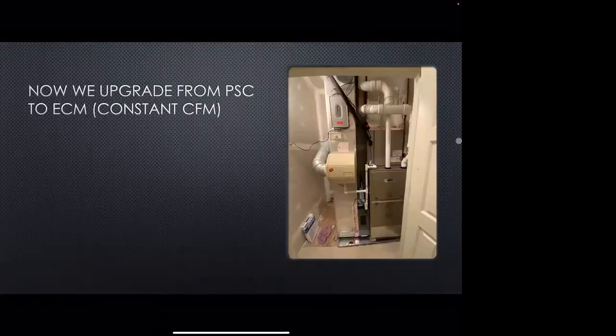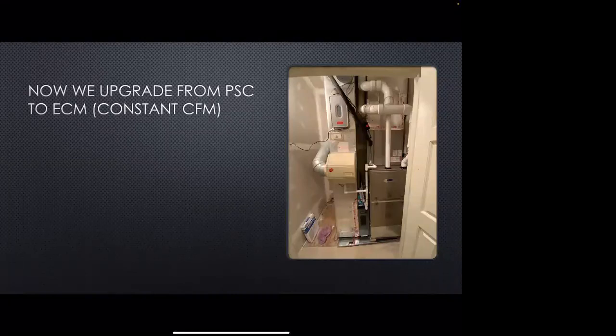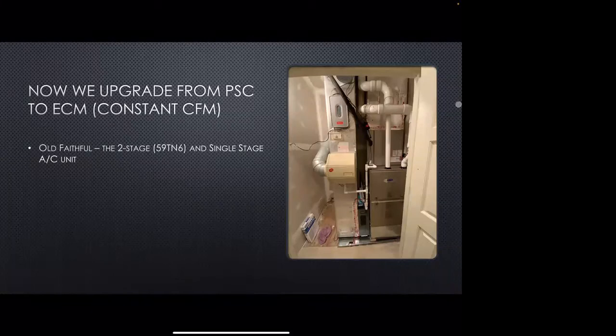So now what we do is, man, we got a furnace that has some impingement, some damage of the heat exchanger that's getting close. The homeowner's like, all right, let's just get rid of it. Let's get it replaced, right? I want to upgrade. I want a new furnace. And we go from a PSC motor to an ECM motor. And we send out our comfort consultants, our sales guys. And we go ahead and we put in Old Faithful. What I like to call Old Faithful is the 2-stage TN6 with a single stage AC. You guys see that quite a bit, don't you?